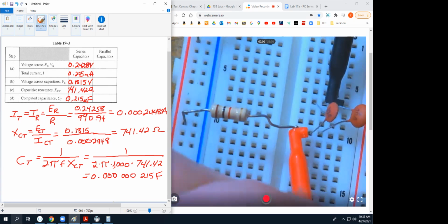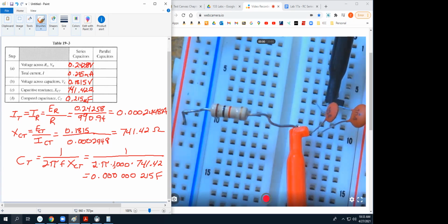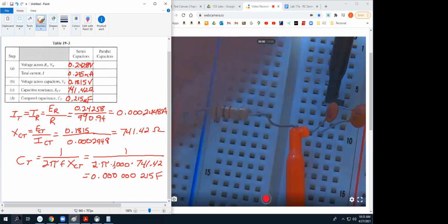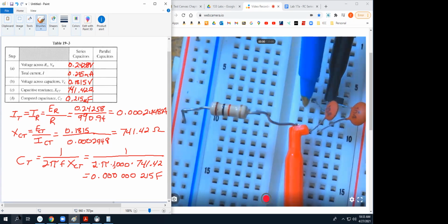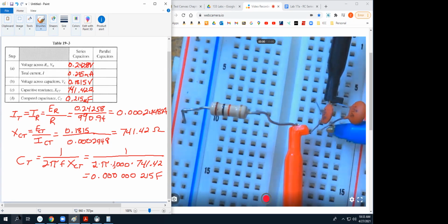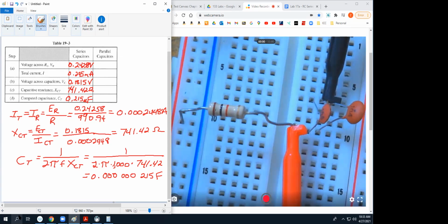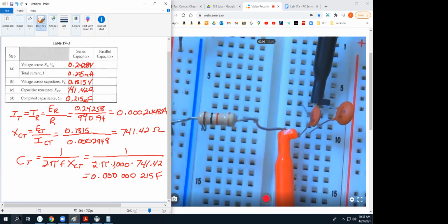I can even grab this resistor right here. That's going to give me the voltage across those 2 points because everything in this row is connected together, right? So anywhere on this row where I take a measurement, it's going to be the same. That makes sense?